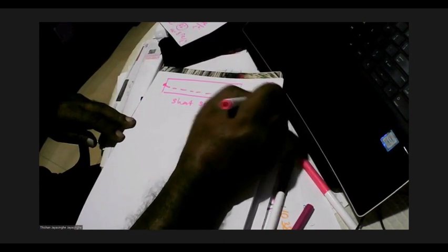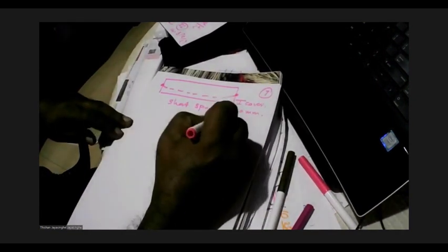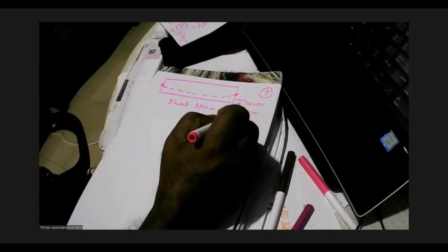But we know one thing, that in the short span direction, we can carry higher loads. In the long span direction, the curve weight is less, so we have to carry less loads. So this is a short span. If it is simply supported, we have the tendons going like this with cover. Maybe 20 millimeters is quite adequate. And then we can make use of wires or strands.